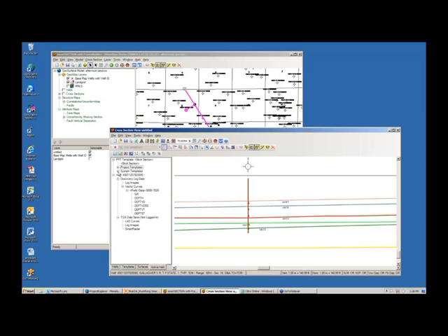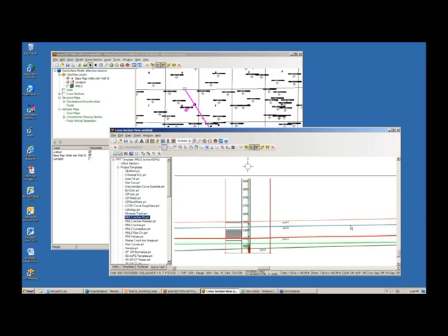So this is just a great tab, don't forget it, to quickly and easily access all the well data in exactly the correct template that you wish. While I'm here, the way you do this is you just select the template you want. You do a right mouse button and you either apply it to the active well or apply as a default log template to all the wells.